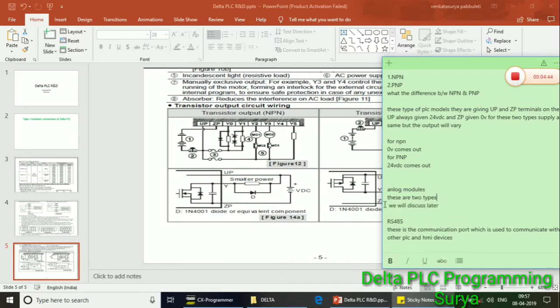Okay, so analog modules are of two types. These are DA and AD. DA means digital to analog and AD means analog to digital. Analog means 0 to 10 volts DC, or 4 to 20 milliamps, or minus 10 volts to 10 volts DC. So we will discuss that later.